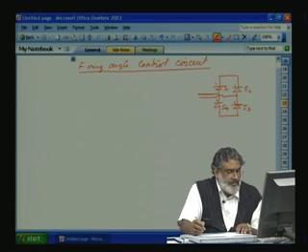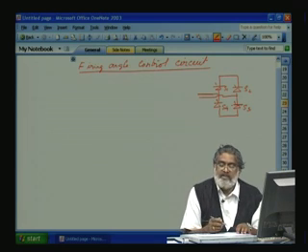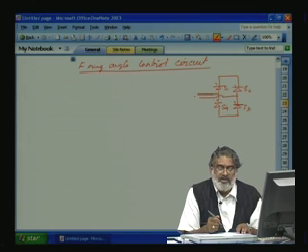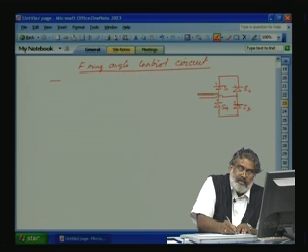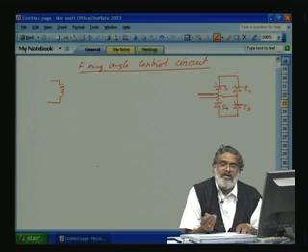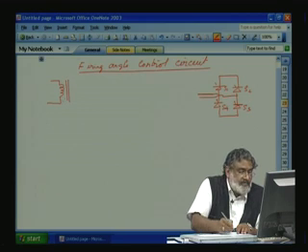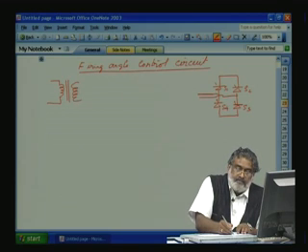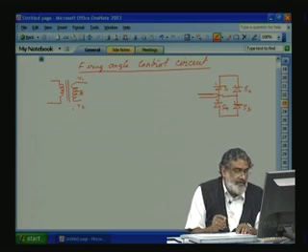Now, how do you control the circuit? All the firing angles are with reference to our main circuit. Mains is 230 volts, so to get the control level we have to step it down. We will have a step down transformer, maybe 230 to 10, that is 230 RMS into root 2 to 10. So you can have a control level of plus or minus 10 volts. We will use a center tap transformer, so V1 and V2.